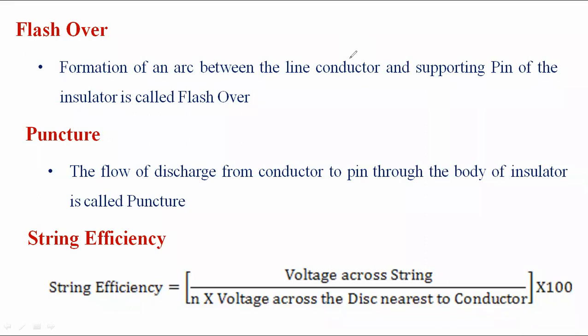And the last one is the shackle type insulator, which is used for distribution purposes. The suspension type insulator is used in the horizontal plane and the strain type insulator is used in the vertical plane. But the shackle type insulator can be used in any position, horizontal or vertical. It is simply fitted on the supporting structure, the pole, with the help of a bolt and nut. The conductor is twisted onto it, for three phase 440 volts.